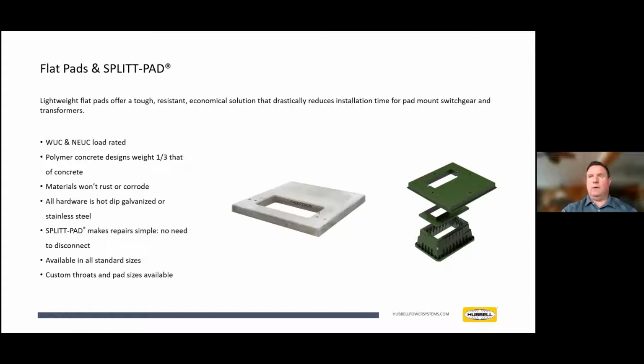Typically you've got enough cable coiling in the throat area to lift that transformer up, still energized. Take a Sawzall to the existing plastic pad, cut that away. And then you can, again, unbolt the sill portion of this split pad and slide the core and coil portion of it underneath the existing transformer, slide the sill portion of the flat pad to mate up with its back end, and bolt it all together and lower the energized transformer back into place.